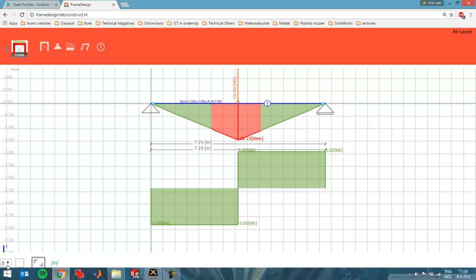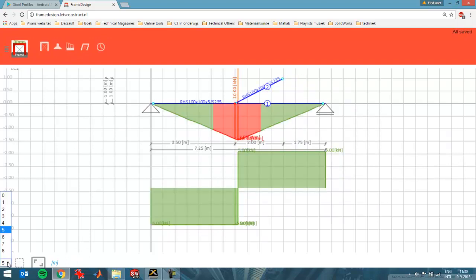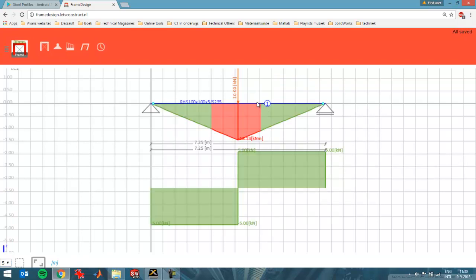And then here are some possibilities as well. Here you can enter the snap points on beam. So if I choose the next beam and I have more snapping points, I'll draw another beam. You can see that it will snap to the middle of this beam, and if you leave this on 0, it won't. So it's the snapping for beams, but not snapping to the raster that you see in the background.